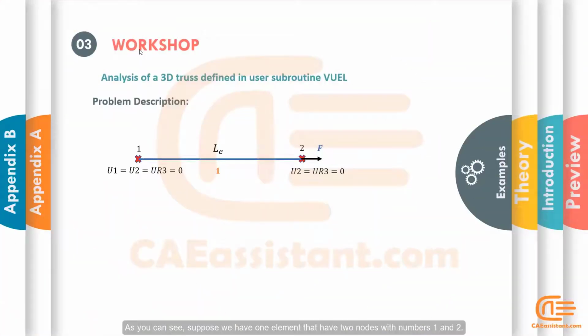The model is a truss that has two nodes with numbers 1 and 2. One side of this truss is completely fixed and U1 equal U2 equal UR3 equal to 0. On the right side of the truss, 2 degrees of freedom is prevented and it is only allowed to move in direction 1. Material properties of the truss are shown here.